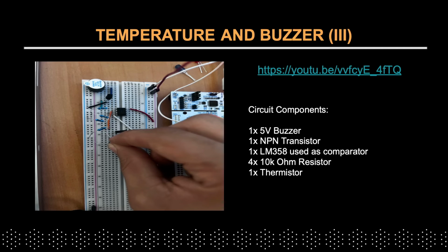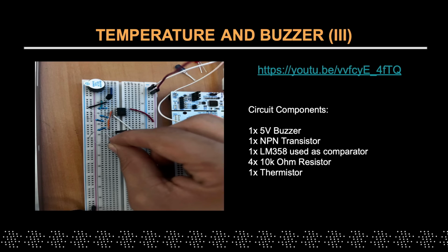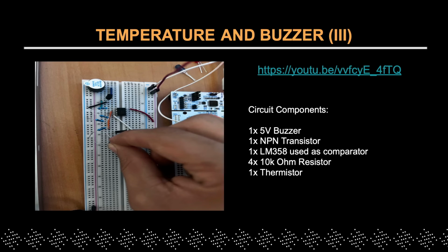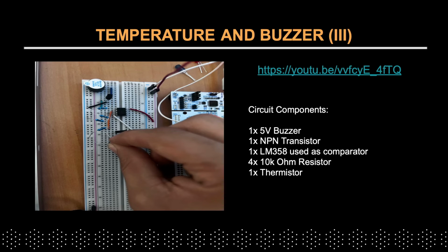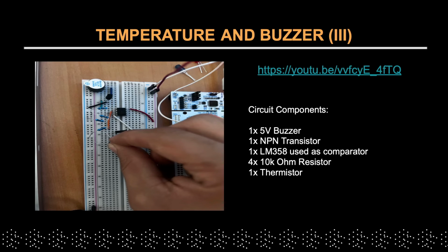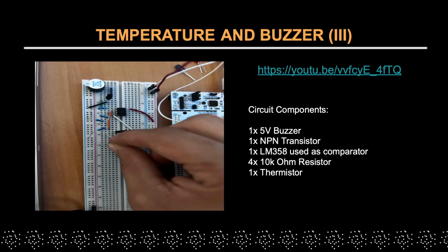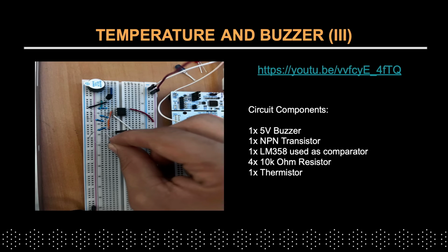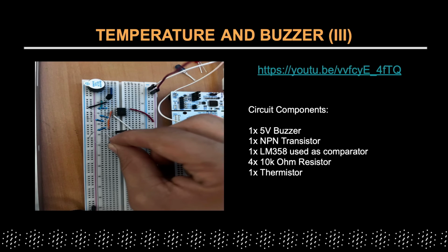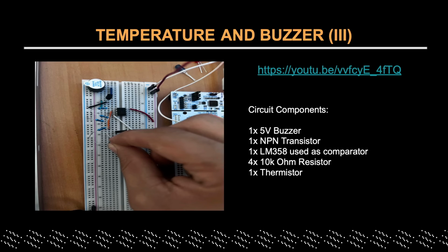When the thermistor heats up, the resistance will decrease, and the comparator will notice this change. As we know, as the temperature increases, the resistance of the thermistor will decrease. So the comparator will notice this change and will notify the user. The output of that will be the buzzing noise.